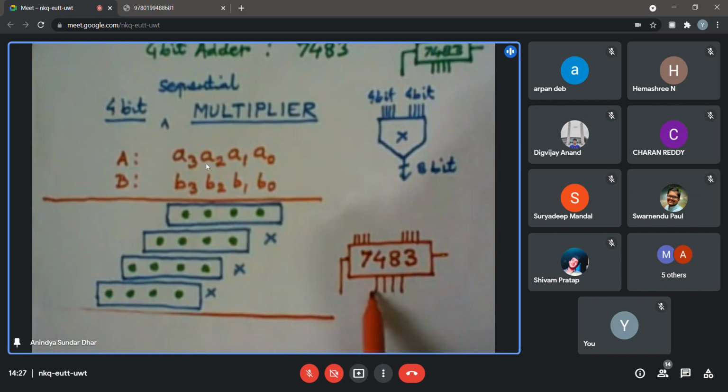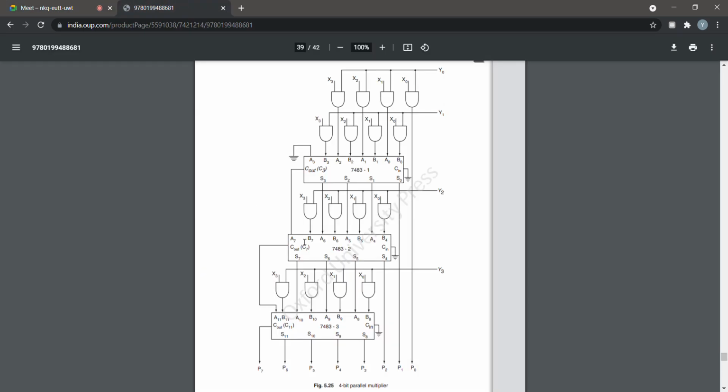So that is what we are having in a 7483, the 4-bit adder, combinatorial adder IC that you have used. So there are 4-bit inputs. The arrows are not visible anywhere clearly, but anyway, they are arrows. So just a clarification. For storing the final output, will you use a 7-bit register or 8-bit register? You will be requiring an 8-bit register, certainly.